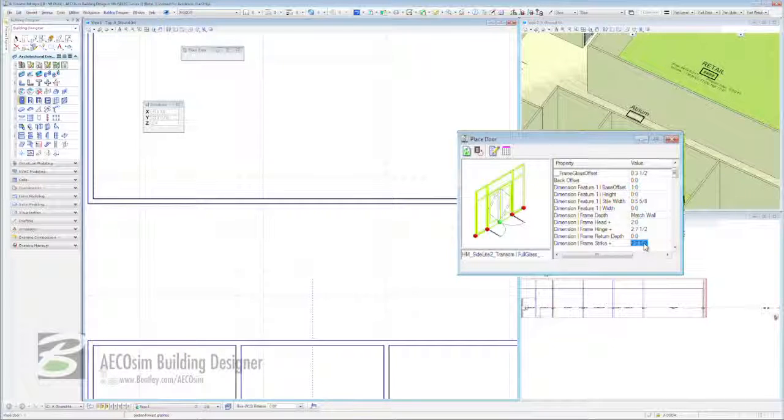And now we have equality all around. But let's go even further, because we're going to scroll down here and you can see absolutely everything that's here. We're going to come to our leaf 1 angle. I'm going to click on there. I'm going to say 45 degrees, and my leaf 2 is going to be 45 degrees. Again, our preview's updating for us immediately.